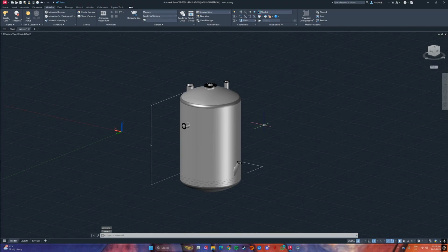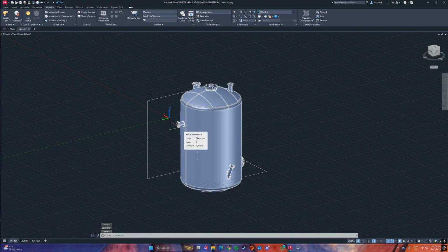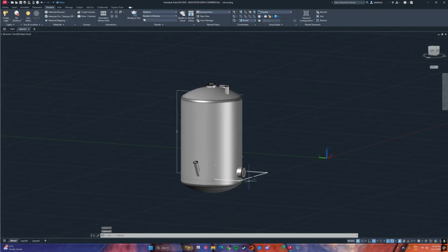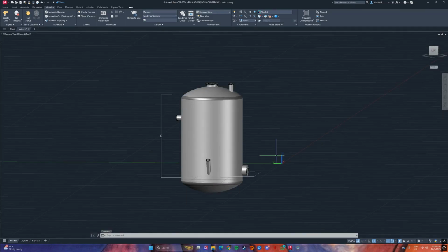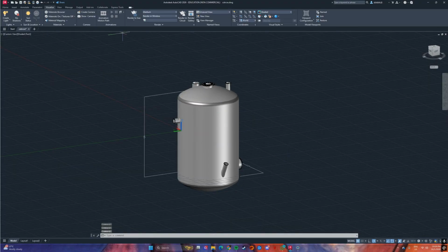And then we also have the product outlet here, where it will continuously remove reacted mixture from the reactor. And we also have the coolant inlet, which introduces cooling medium into the tank. And then we also have the coolant outlet here, which will remove the coolant after heat exchange, which will ensure effective heat removal and supply.